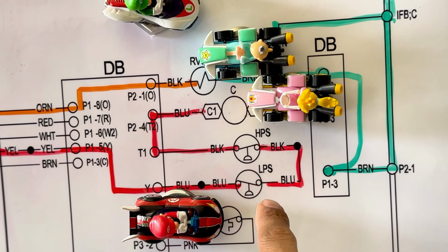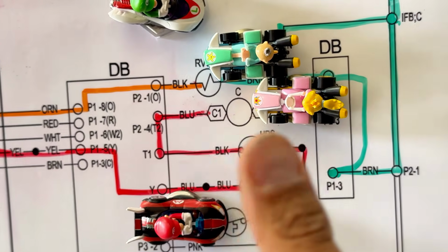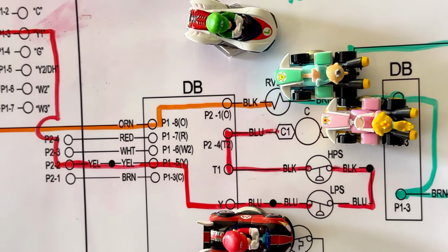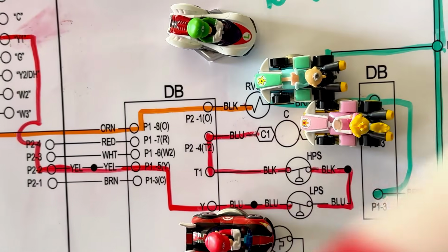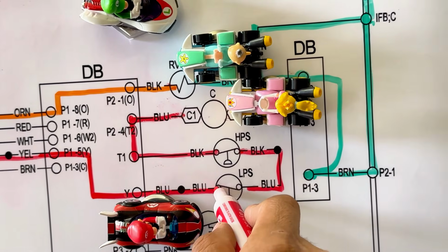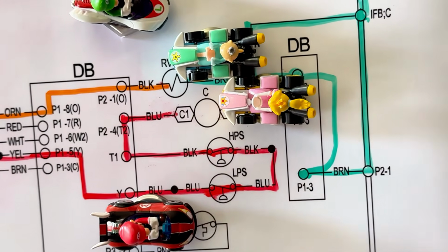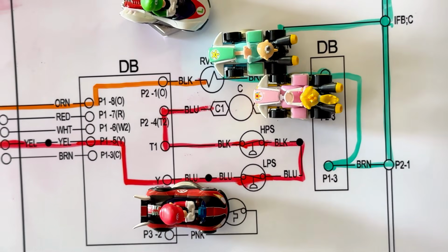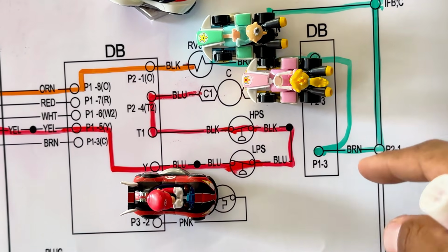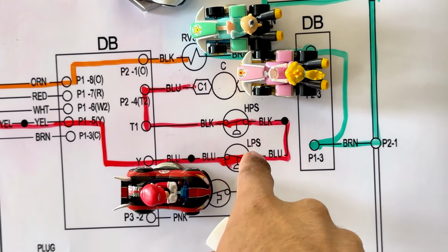But this low pressure switch, if the pressure drops too low because it's low on refrigerant, or you have a dirty filter, then guess what? That bridge is going to be open. So right now, just for the heck of it, let's say we have a good functioning unit. But let's say I'm low on refrigerant. If I'm low on refrigerant, my pressure drops, or I don't change my filter. That's a low pressure switch.